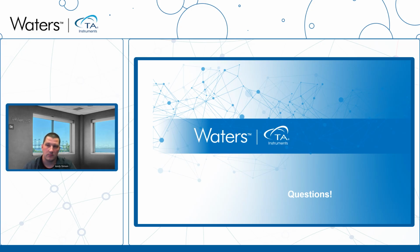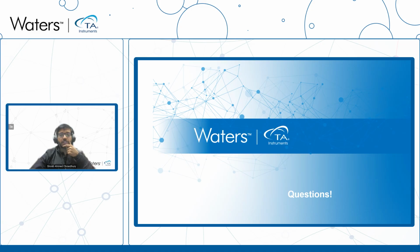That's a good question. Even if parts are designed with knit lines, and you're assuming that your knit line is located at lower stress regions, it will still not be absolutely zero stress. So there will always be some stress, and without quantifying material performance at that stress level, you actually do not know if your low stress is low enough for long-term reliable performance.